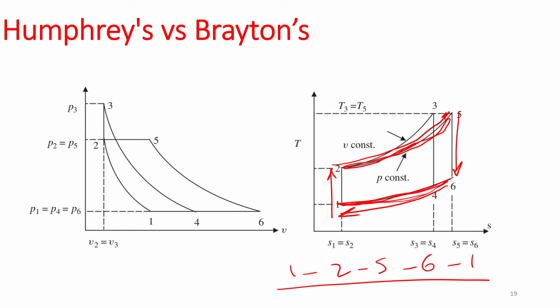So this part of the cycle is not really there because you are exhausting into air. Air is not coming back, but for the design analysis, we usually assume that there is a cycle going on. This is the feature of open cycles: your exhaust doesn't go back to the inlet. So I'm sorry about that mistake, just make sure that you are clear. We go from 1 to 2 to 5 to 6 for the Brayton cycle.